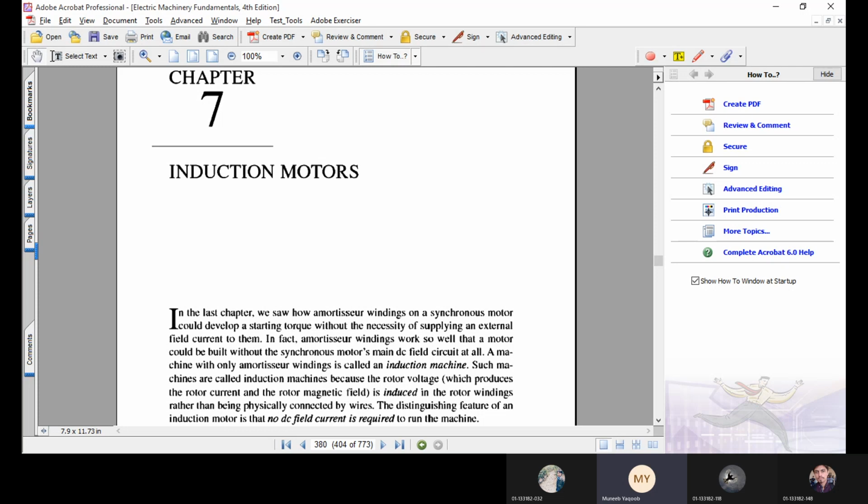So the relative motion between the two becomes zero. Due to this zero relative motion, the EMF induced in the rotor's winding becomes zero, and hence the magnetic field of the rotor becomes zero. In this situation, the rotor feels a drag force and slows down. So it never reaches the synchronous speed for a longer duration.